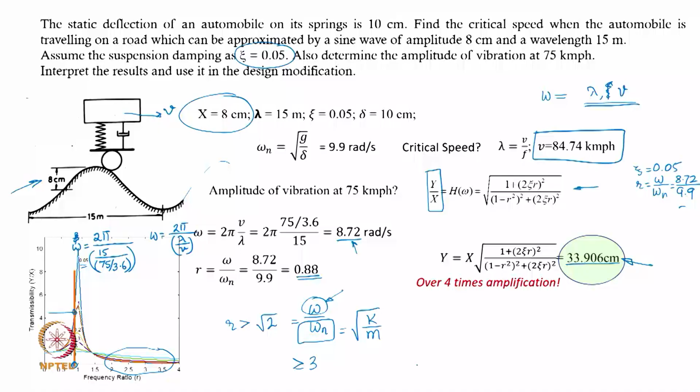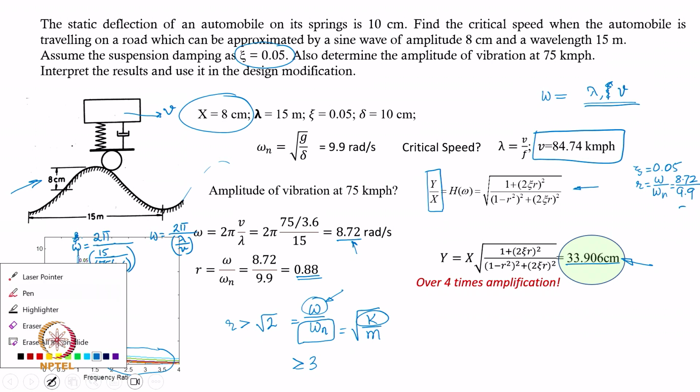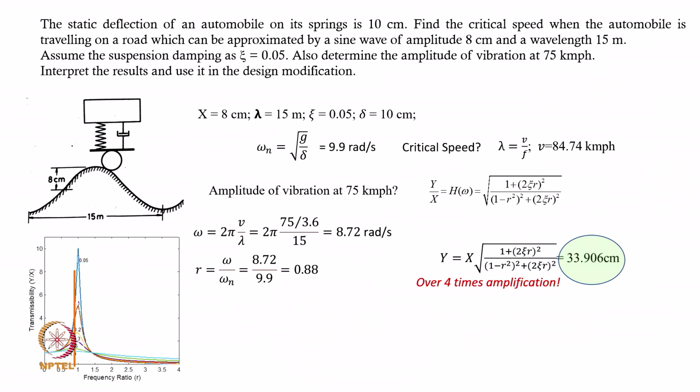Increasing the mass. Now, increasing the mass has its own problems. Increasing mass means you get a pillion rider, right. So, you are going alone and I cannot change the mass of the bike. So, one possible option is to redesign, and this is the most common and most practically viable option compared to increasing or changing mass. And so, what we are looking at here is that I would like to redesign my isolation system to change the omega n value.